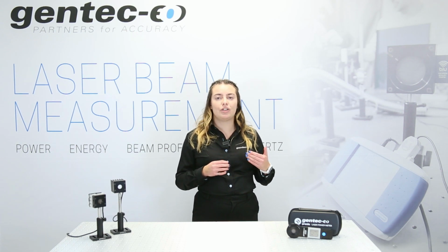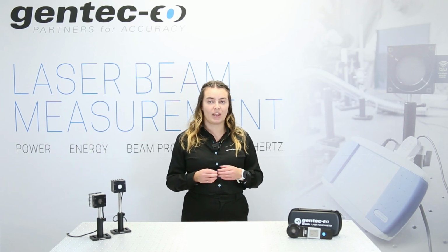Beam size is useful to know how big the laser beam is in your process. Most applications require to measure the beam size at the location we call the waist, since it is the place where the beam is the smallest. Beam size is useful to know exactly what area of the material will be affected by the laser.